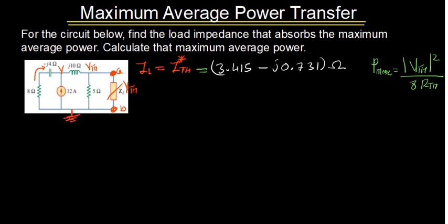So here I'm going to say let this be I1. Then from V to V Thevenin, let me name this I2. Then from V Thevenin coming down, let me name this I3. So I have a node here and a node here. What I'm going to say is at node V, if you apply nodal analysis there, you're going to have minus V divided by what?